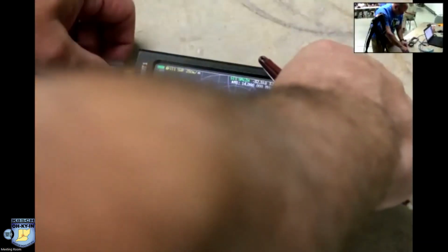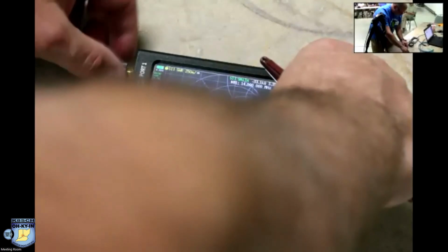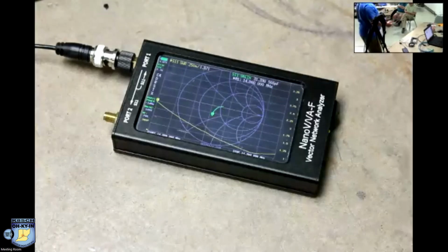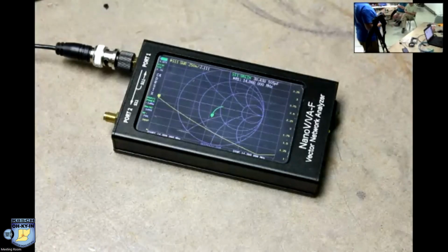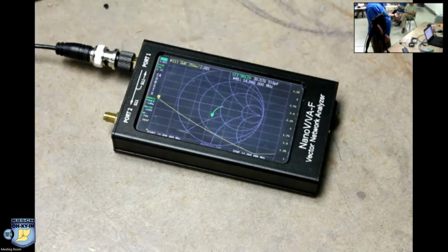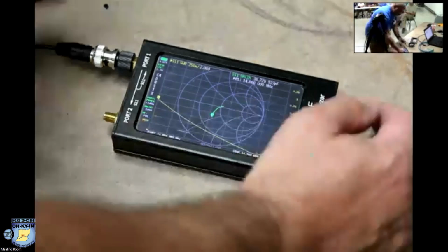Yeah, I was talking about this earlier. This was connector hell. I mean, this thing has an SMA on it, but I have BNC because a lot of the stuff that I'm using the BNC for is photo equipment, and you need a BNC. And most of the stuff's with BNC. So there, you see the frequency response on this guy here. Not too shabby, because I think I was using it for 40 meters the other night.